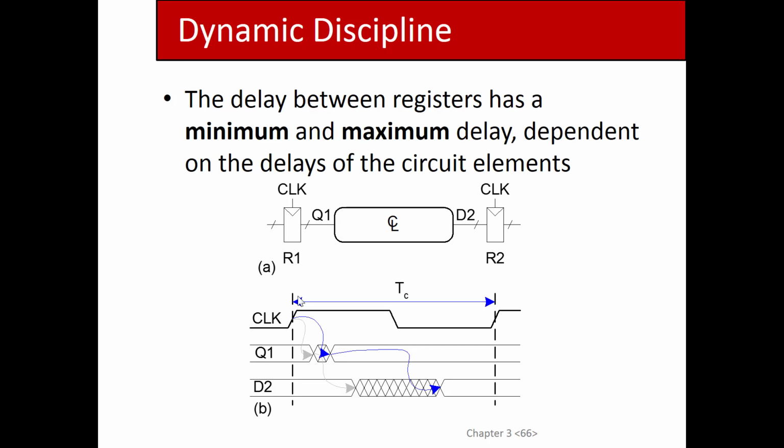Okay, so here's a typical data path, and this is the data path that makes up a CPU. I mean, a CPU is literally nothing but a collection of these data paths. You've got some sort of memory that's connected to logic that's fed into another memory, and these data path operations are what execute individual instructions within a CPU. So you have a clock edge, which in the notation here is TC, clock period, I should say.